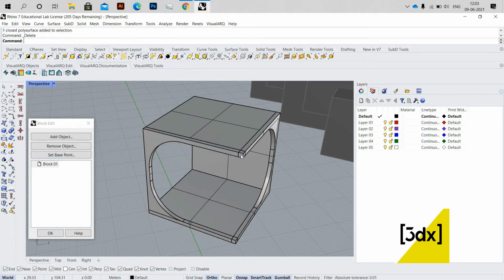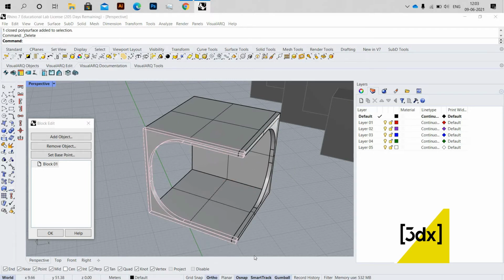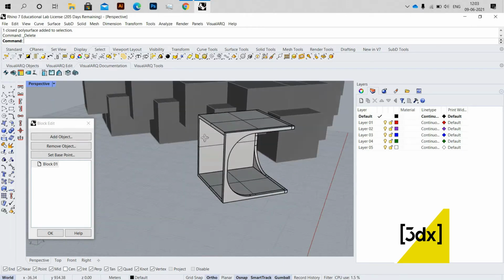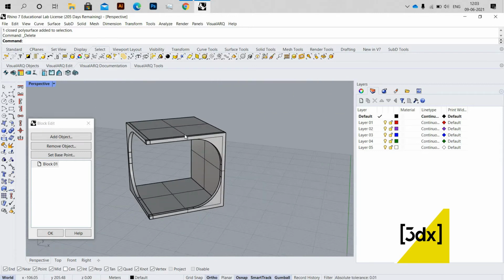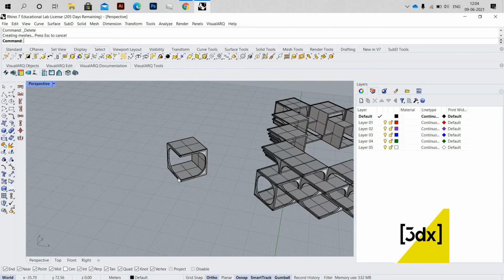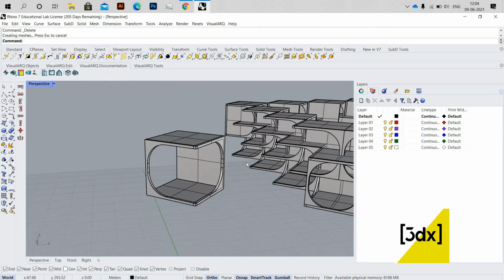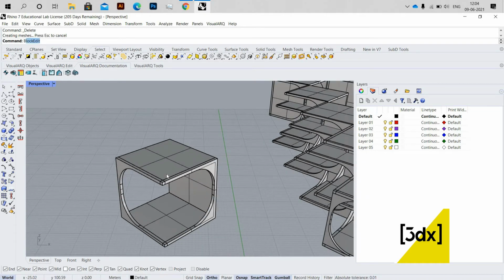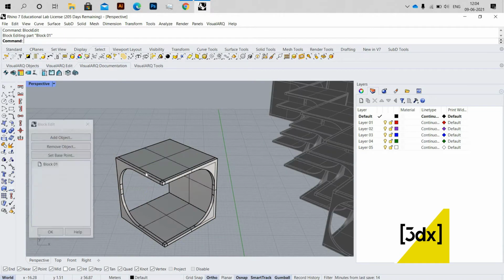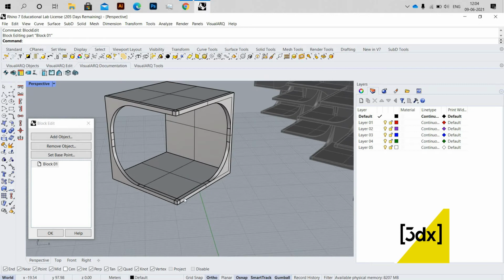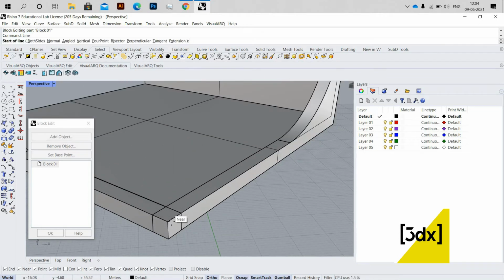So I'm using boolean subtract to get the overlapping surface. So these are the overlapping parts. I don't want them to overlap and make my model heavy, so I'm trimming what is not necessary. So this is fine. I press OK. When I press OK, you can see that all the cubes which I drew inside have been changed according to what I used. So I'm going to enter into block edit mode again. As I said before, whenever you edit a block, go into block edit mode. If you do not, then your work is useless, because it won't give you a change.